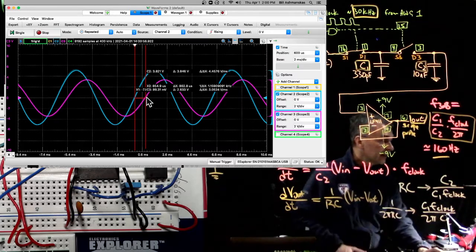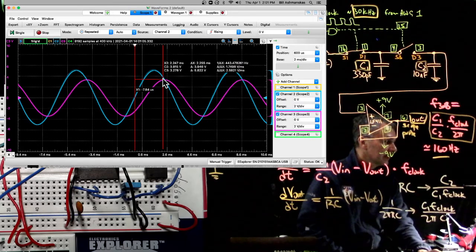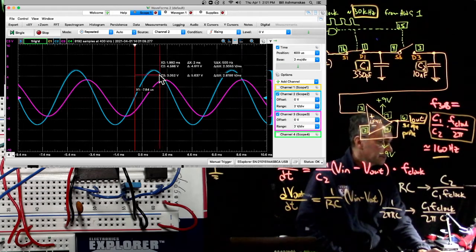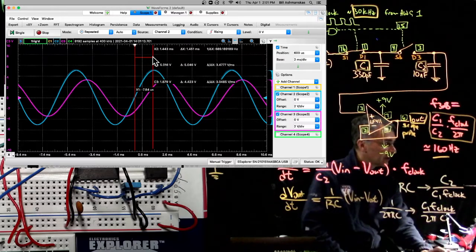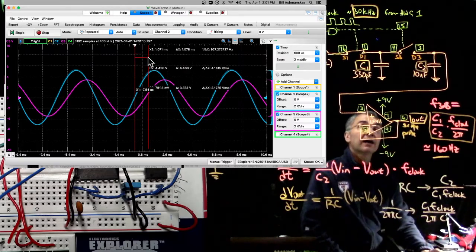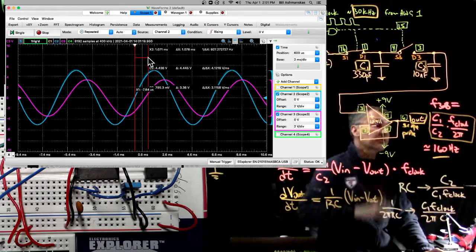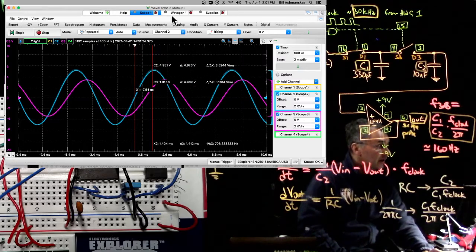So it seems like F3dB is a tiny bit smaller than this 160 hertz that I found here. But yeah, we're pretty close. All right, I'm going to say that's close enough. We could try to measure it precisely. I think it's close. Also, I don't know how close to 330 picofarads this capacitor is exactly. I think they're like 10% capacitors.